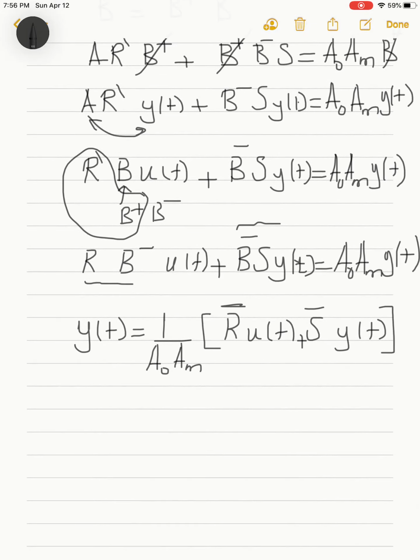And we'll do what we did before. We will assume that this is a filter, and u of t or y of t will go through that filter to obtain a filtered signal uf and yf, and R bar and S bar will be the polynomials that will appear in the equation for the estimator. So we can write R bar star.